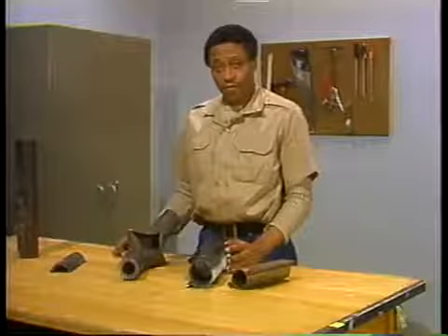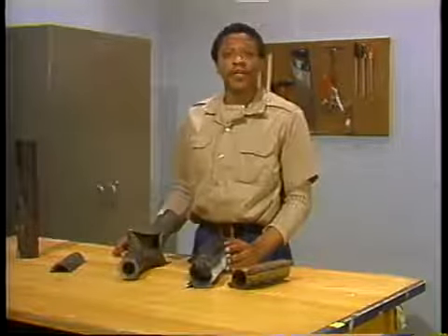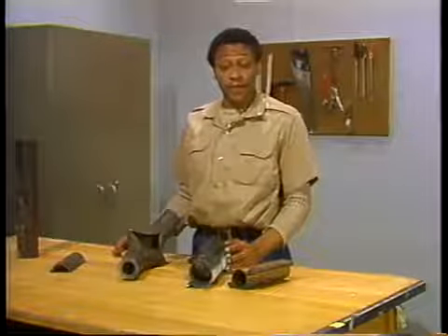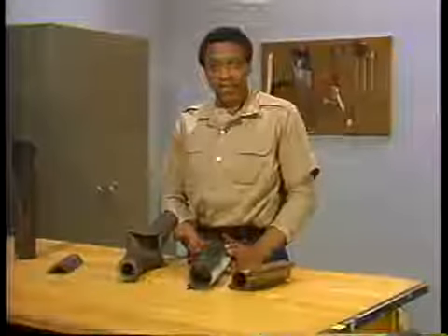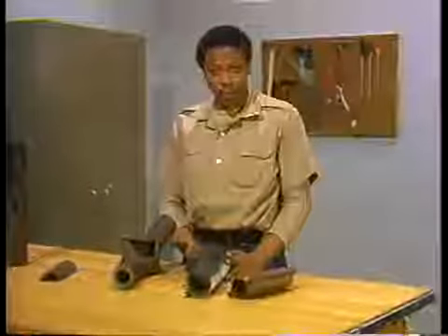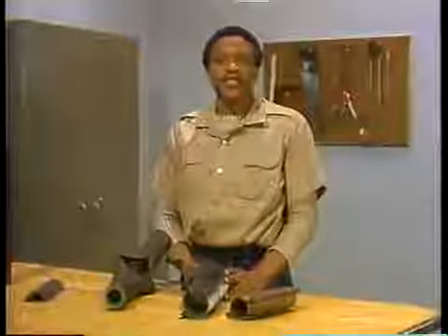Now that we've covered the basic causes of tube failure, let's go over some of the types of tube failures and deformities. Deformities are irregularities in the tube metal that can lead to tube failure. First, let's examine different kinds of failures that cause leaks. The first type is a rupture. There are three kinds of ruptures: thin-lipped, thick-lipped, and double-ended.